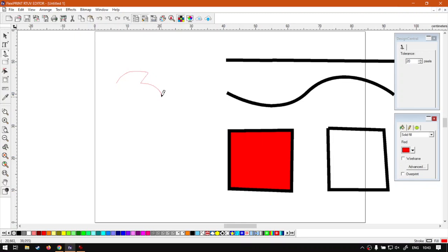And that is where our first shortcut comes in, which is quite handy. We can simply keep control held in and then run back onto this path, but make sure you keep your left click still held in, because if you let go of that it will complete the path and you won't be able to erase anymore. And then like that we can simply carry on with our shape. Once again, if you make a mistake, you can simply use control, correct it, and then complete it.